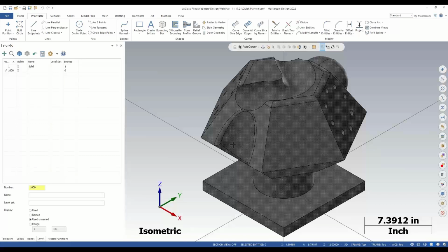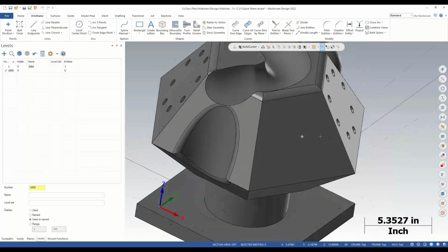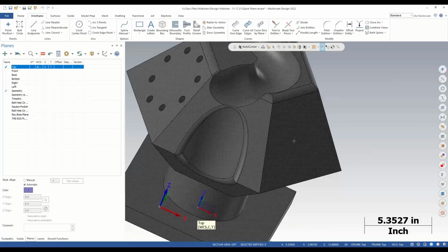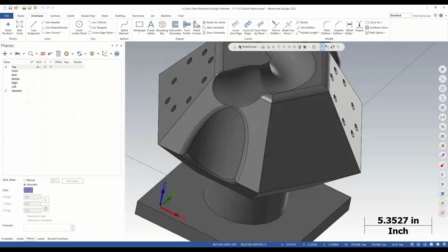But to give you an idea of where this came from, because no idea comes from a vacuum, we had a couple customers who do a lot of design work in Mastercam where they want to create a feature right on, say, this face here. So they would have to go into the planes manager, create a plane from a solid face, pick this solid face, and then create the geometry. And every time they went to draw, say, a circle, they would have 4 or 5 different planes for each orientation of that circle that they had to draw. So in 2019, they introduced what's called Quick Plane.